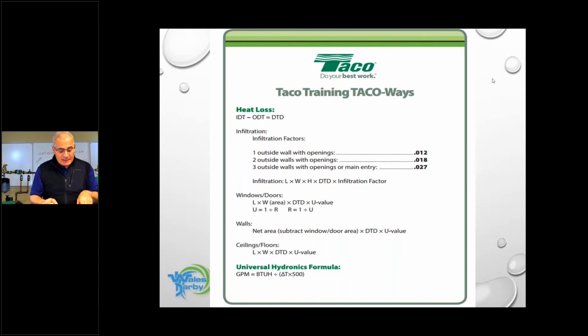All right. So next would be the ceiling. The other thing we have to know is this room, does it have conditioned space above? Does this have conditioned space below? This could be a room that's on the 2nd floor, so I'd have no heat above. This could be a room that's over the garage. So not only would I not have heat above, I may not have heat below. This could be in addition to a house where maybe they're going to have it over a crawl space with no heat above. We need to know this. So for today's example, we're going to make believe that we do have heat below.